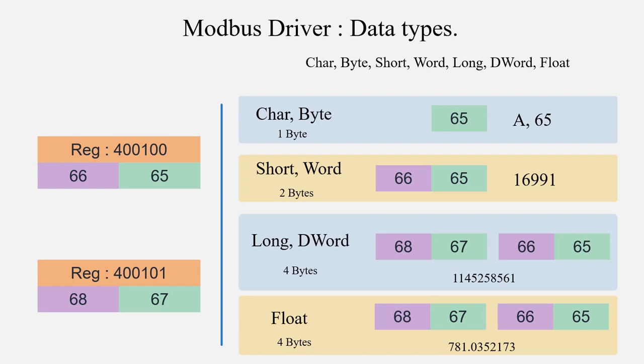Data types short and word represent 2 bytes or single word. As Modbus register is also one word data, it will get stored properly in tags with these data types. Data type short will be treated as signed and word will be treated as unsigned.